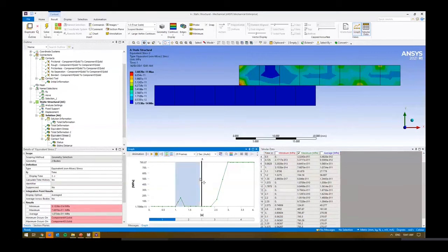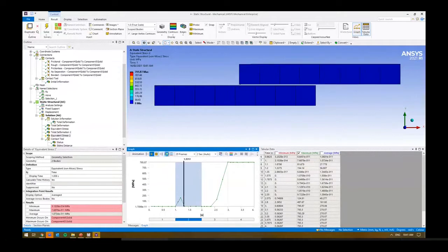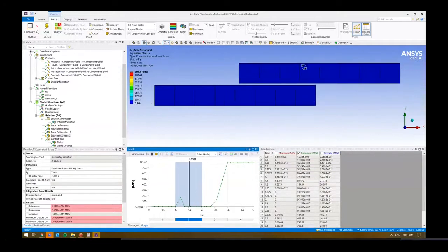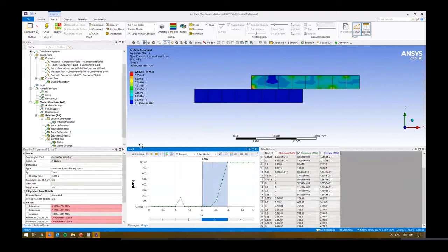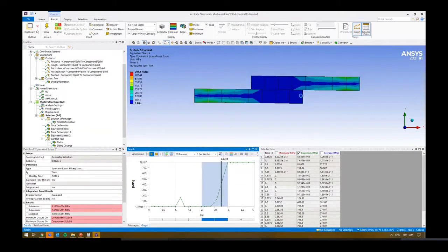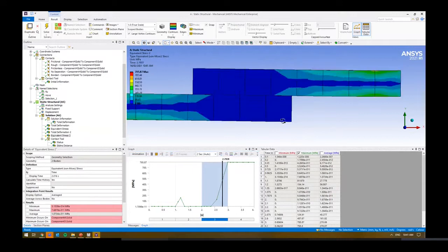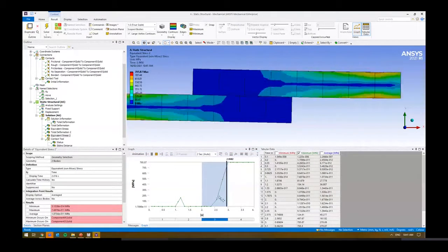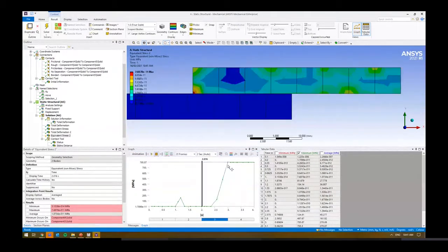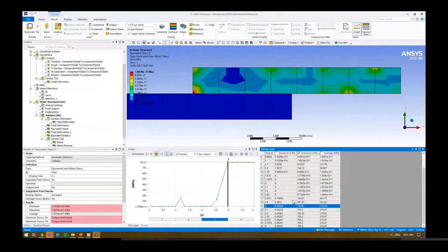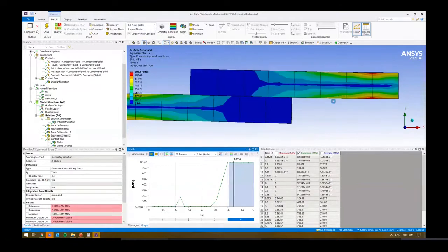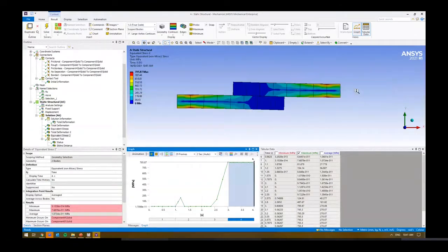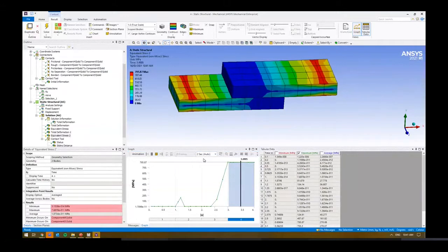Even for the second step, we're just simply coming off. It looks like it's sticking a little bit and kind of coming off. Now stress starts to increase as we start to impact, and we start to make some impact with that surface. We'll see it goes from 0 all the way up. We can track what's happening, and I can look at that specific value, go to the maximum. This is what the stress is. Then in that particular component, because we've got the whole thing stressed, the stress values are relatively large and it's kind of sliding in.